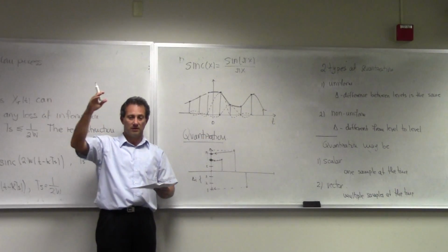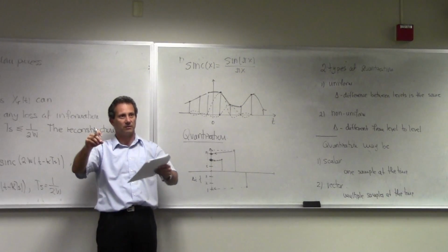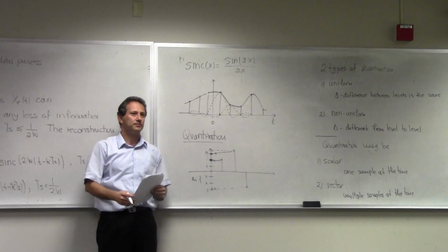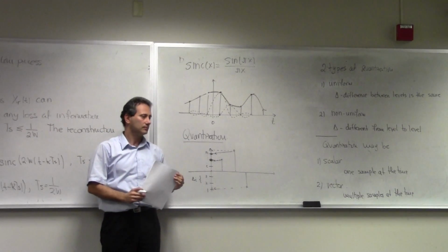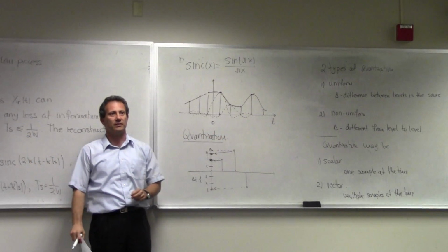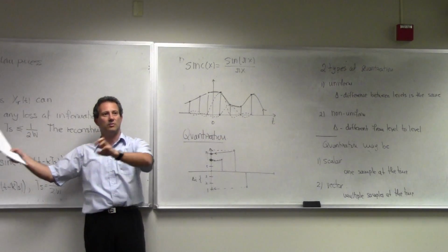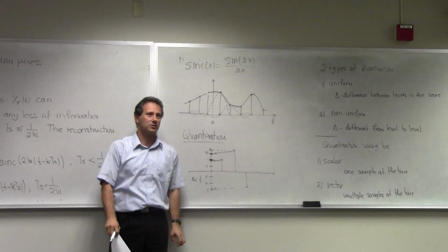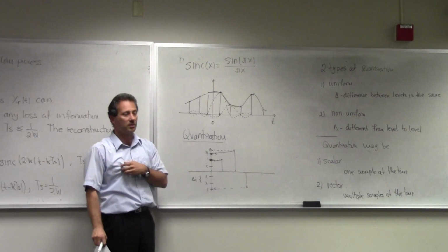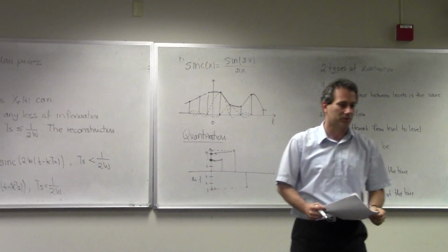And then the receiver has a book of all the allowable vectors and it goes to vector 5 and here come all of these 10 samples. So instead of sending 10 samples, you just send number 5. You and I know what the 5 is, so you go back to the code book and you pull out the whole word that is associated with 5. So that's one of the principal ways you do the compression in these. You have to do it smart, and there are code books and there's a whole theory.